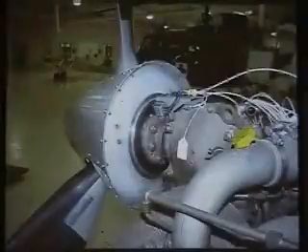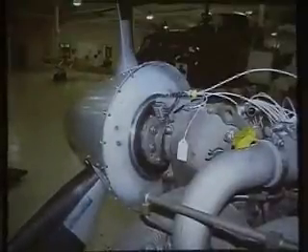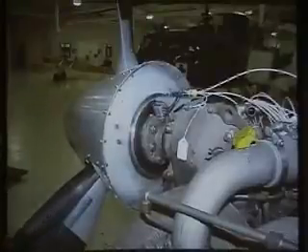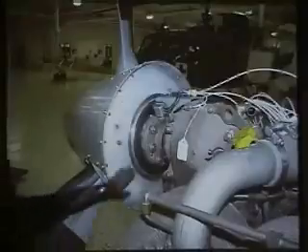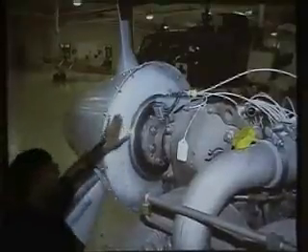Here's a picture. You can see the rubber boot right here. It's nice and smooth on a propeller that's a hot prop. On an alcohol prop, you'd see ridges right here for the alcohol to help get spread out towards the tip. On hot props, the rubber boot is smooth, and I've got a closer one you can see. Here's the propeller spinner. Here's the back plate of the propeller spinner. I'm going to zoom in here on the next shot.